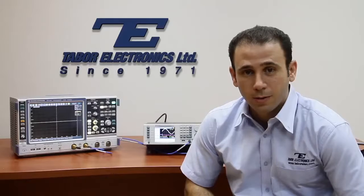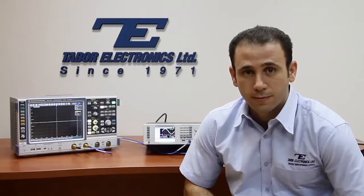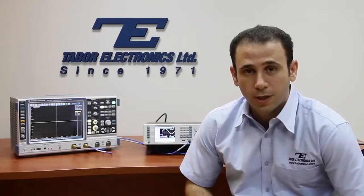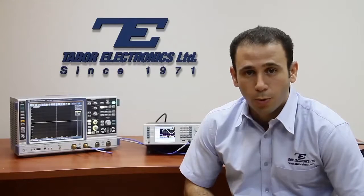Today we'll learn about how to simply generate sequence waveforms with Tabor's Wavexciter series. Sequence waveforms are constructed from two or more arbitrary waveform segments, which can be combined, mixed, looped, or nested in order to create complex scenarios without compromising valuable memory space.